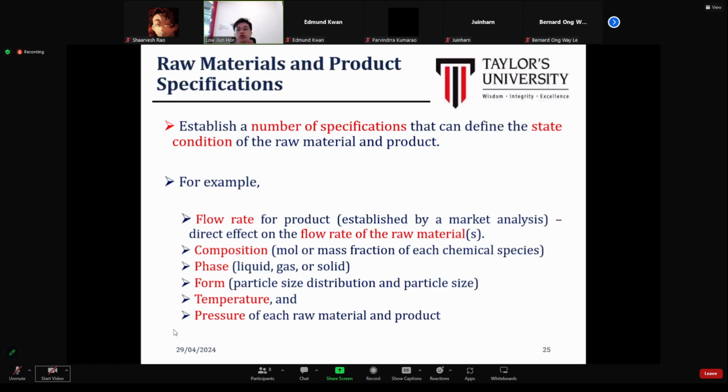And also, similar to what I told you last week in our previous lecture and tutorial, later when you have finalized your chemical design and want to proceed to design the mechanical part of the unit operation, there is some information you also need to know. For example, the composition of the process stream you are going to handle, the physical state of the process stream, the temperature and pressure in the reactor or unit operation, or even the volumetric flow rate or mass flow rate inside the pipeline.